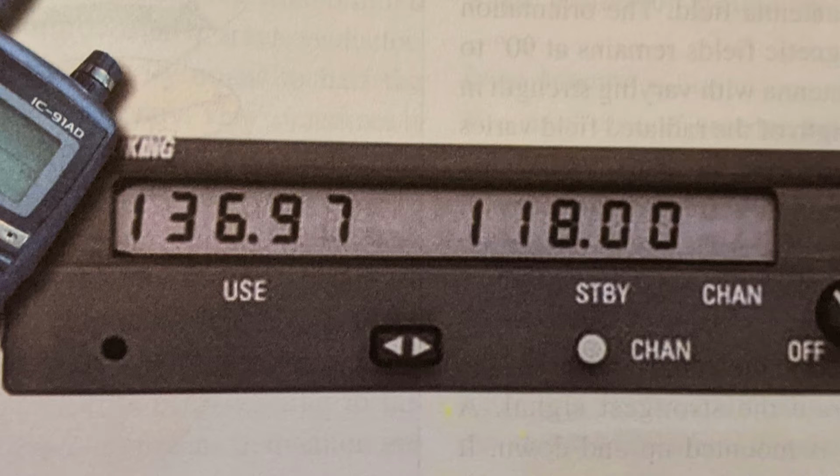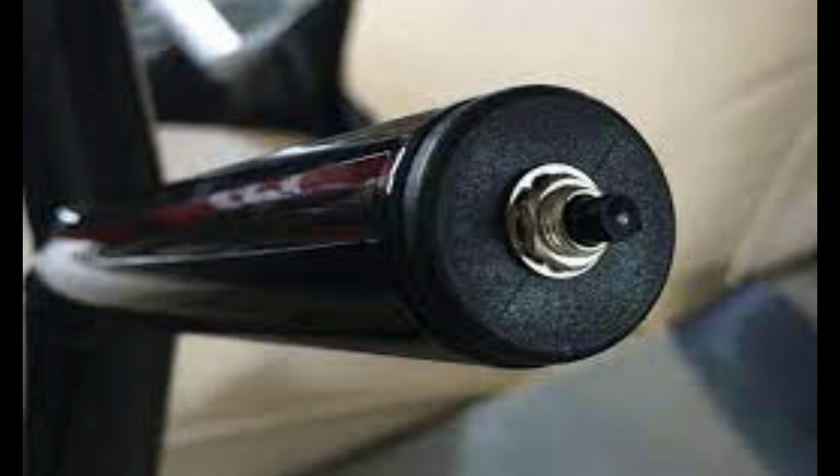Transceivers. A transceiver is a communication radio that transmits and receives. The same frequency is used for both. The push-to-talk switch blocks the receiving circuitry and allows the transmitter circuitry to be activated. This saves space and the number of components used. Transceivers are half-duplex systems where communication can occur in both directions, but only one party can talk while the other must listen. VHF aircraft communication radios are usually transceivers.